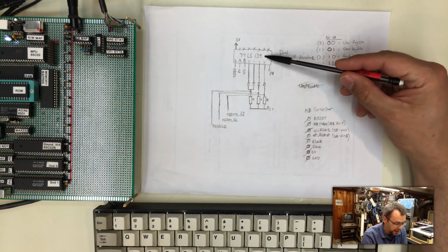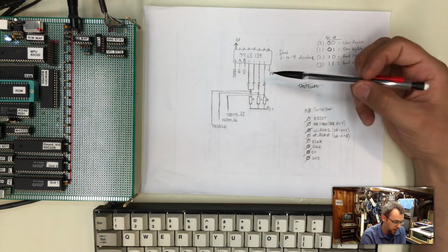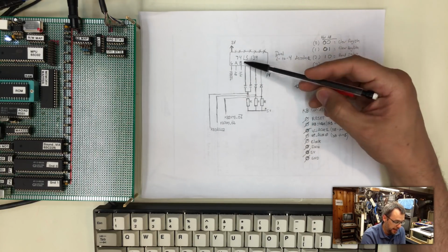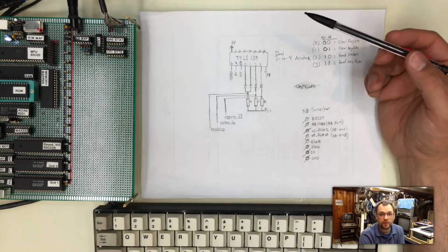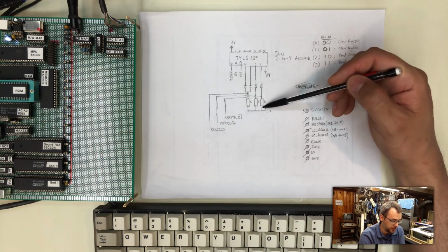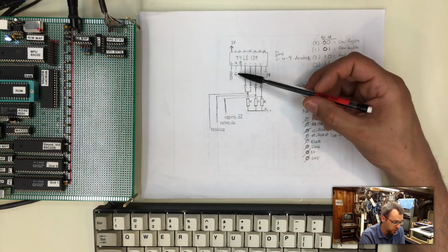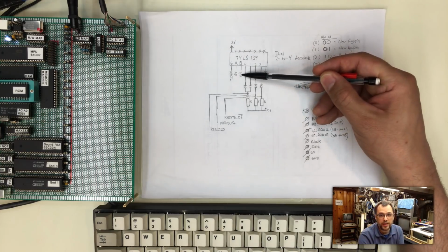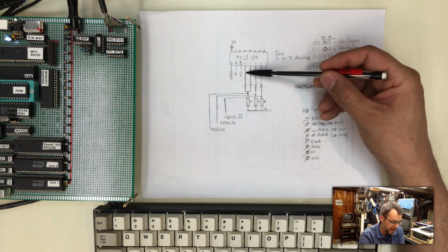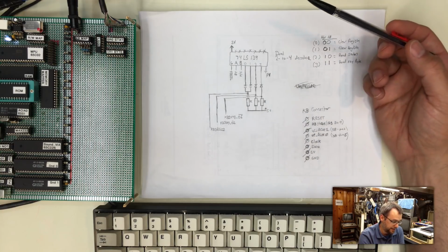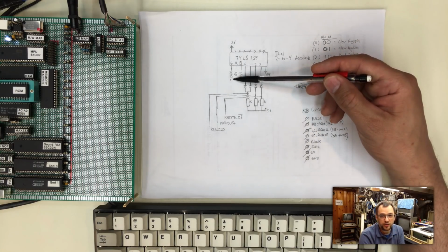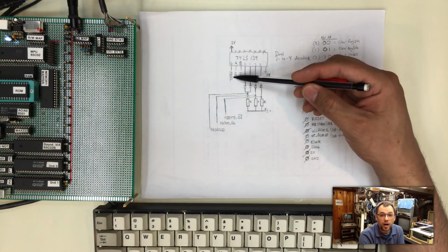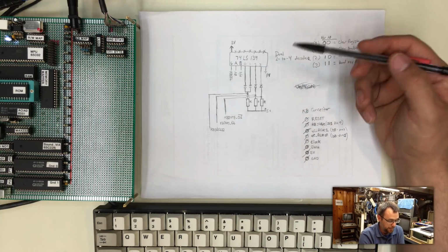I used a 74LS139 chip that can take two inputs, A and B, and give us four outputs. Basically, it takes a 2-bit value and gives us a 4 selection output. Because the only two lines I really need to select on are the first address line and whether we're reading or writing, that worked perfectly for the signals here that I had to send out. Now, there is a third signal, if we remember from the last time I went over this, the keyboard select signal that I was using on the ROM to determine whether I was outputting these values or not.